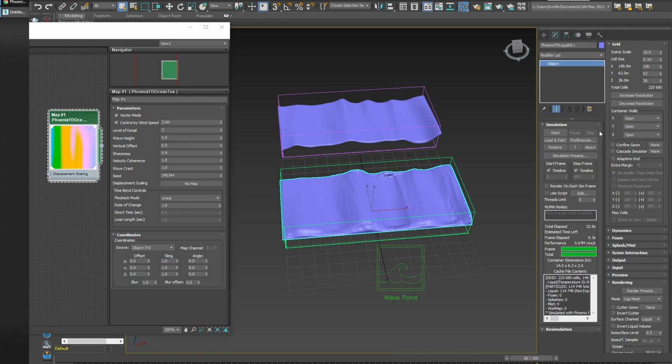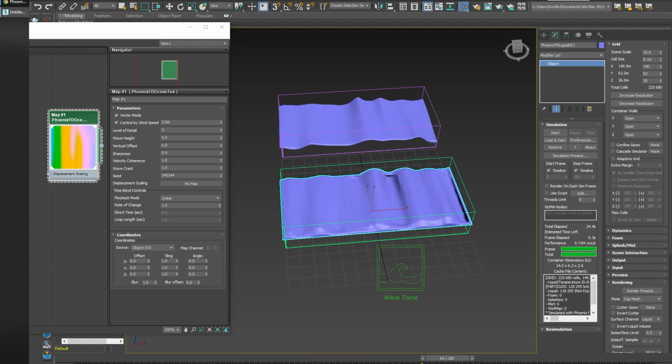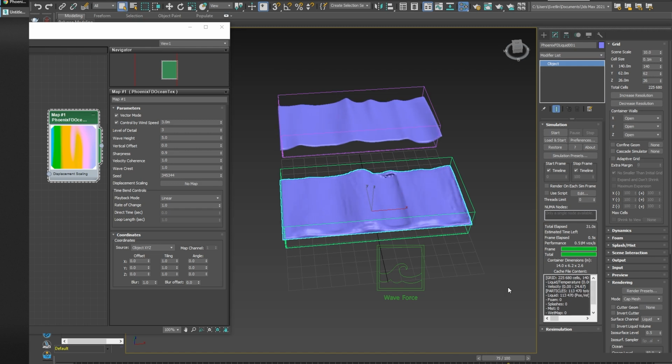And just the opposite, if I decrease the scene scale, then the gravity would have to do less work in order to pull down these waves and just flatten them. So when the scene scale is low, it would be harder to recreate the ideal ocean shape. But when the scene scale is high, you get these tall waves which take a long time to crash down.